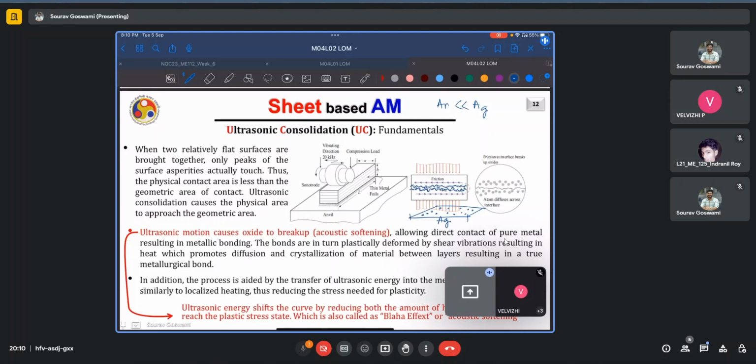However, by the use of this ultrasonication process, the friction and the ultrasonic waves may actually help to break up the oxide which is present on the surface. We know that the surface of metal up to several micrometers of thickness consists of several layers such as the oxide layer, the Beilby layer, some thermally deformed layer before we reach the nascent metal.